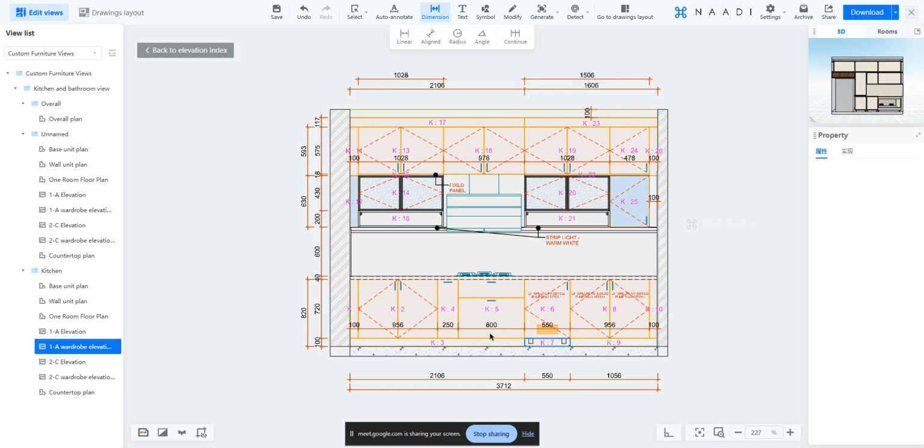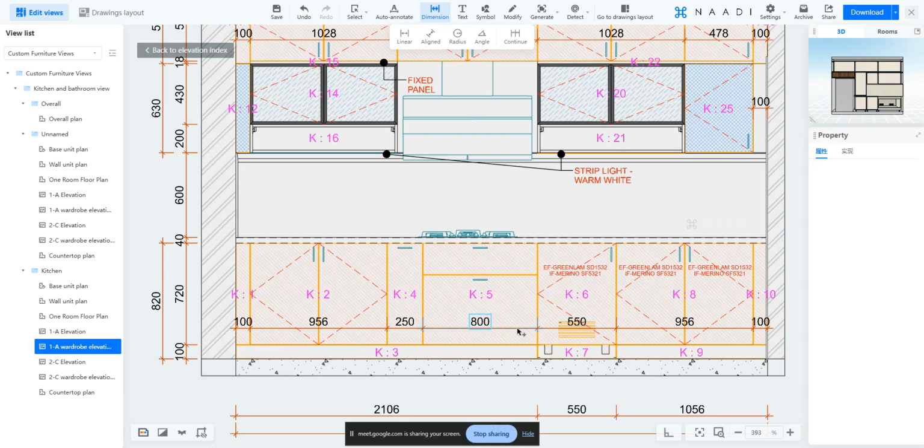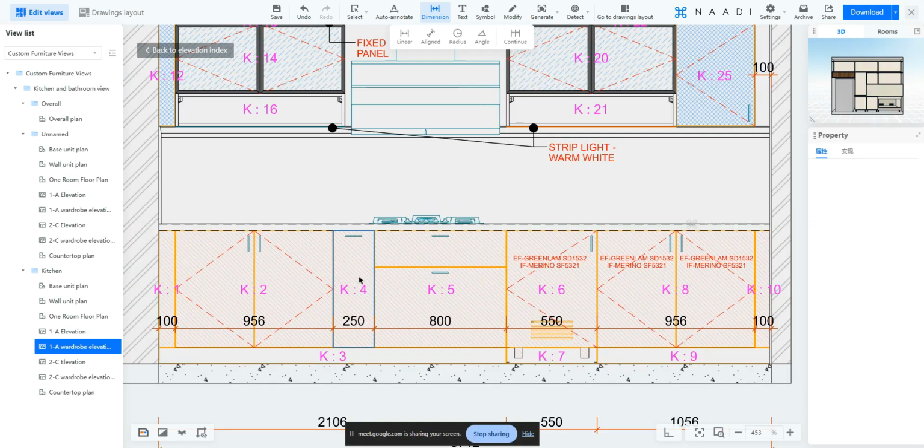For which one? For drawers, drawer heights, drawer fascia height. Got it. That's a really good question here. For the drawer fascia alone, there are two things: your external drawers and internal drawers. For the external drawer fascia and internal for both now, these bifurcations won't be added. The auto-generated dimensions won't be seen there. For that, you have to manually add a dimension.